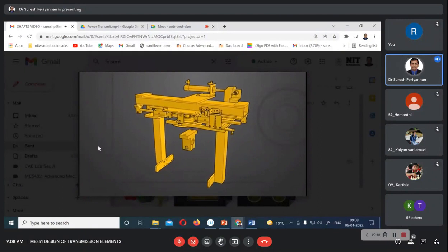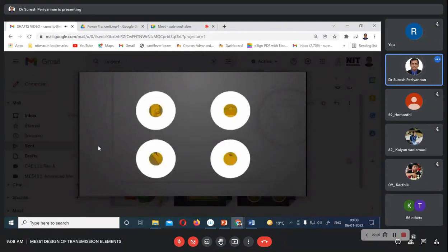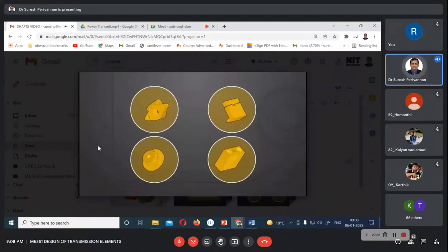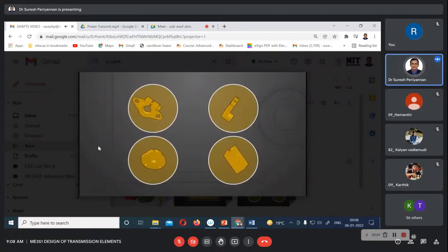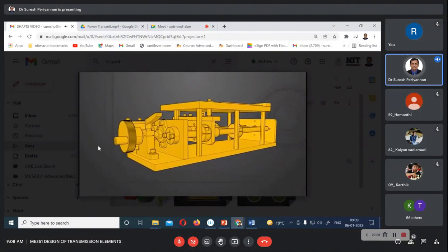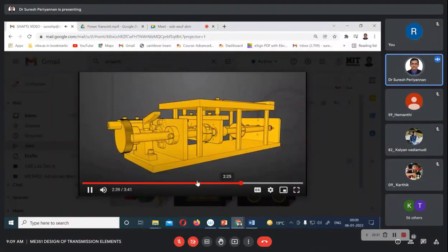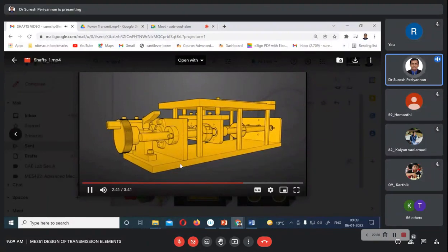Shaft supports are also used in the application to position the linear shaft in a precise location. As you guessed, these are also available in various styles and can be configured with extreme precision. This next application depicts a positioning mechanism. The hand wheel drives a lead screw, which converts rotary to linear motion. The linear shafts are used to help support the load and prevent rotation caused by the lead screw.